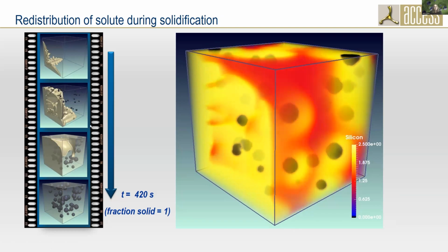And here we are at the end of the simulation, and you see we only have graphite nodules in austenite, but it seems that there is still a dendrite pattern. This is because these patterns are just frozen in, so you still see the history from the old microstructure.